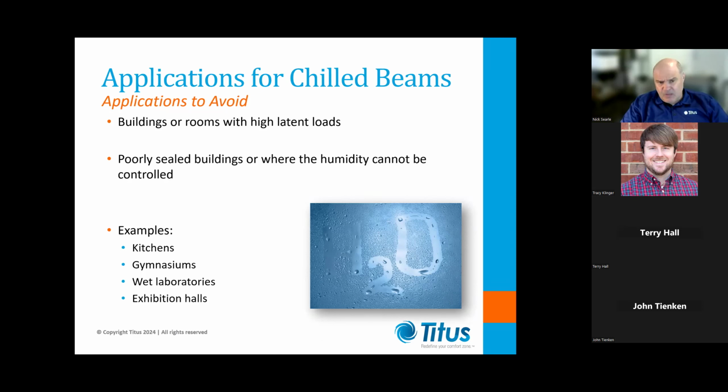A few years ago, I worked on a project in Nashville, Tennessee. It was an old historic building, which was extremely leaky. One of the major engineering firms around Nashville was tasked with designing this building. It was a renovation, and they couldn't change the interior of the building too much because it was a historic building. They found that they just could not squeeze in a conventional VAV system. So they were forced down the route of using active chill beams in this very leaky building.